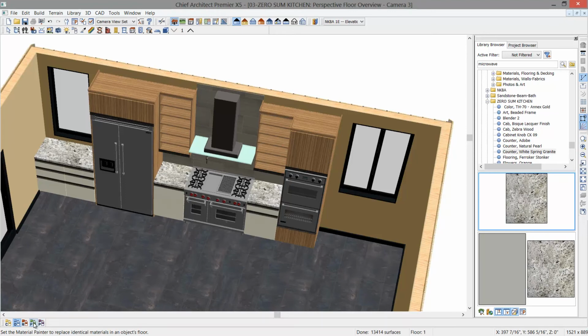And the final material selection I want to change, let's change our crown molding here. Let's use the black off of the window casing. So I've selected my material eyedropper tool in the upper right hand section of your screen. Click on the molding or the casing of the window, and let's change that to a full paint mode. And we'll just paint this molding around here. So we've got those components.